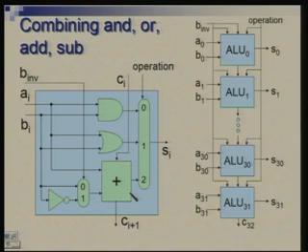Okay. Now, here is a cascade of 32 such units, which are called ALU 0, ALU 1 and so on up to ALU 31. So, you notice that on one hand we have this B inverter going to all of them, and particularly in the first unit it goes to 2 positions, the initial carry position and the BInv position, and this operation control also forms another control input which goes to all of these.